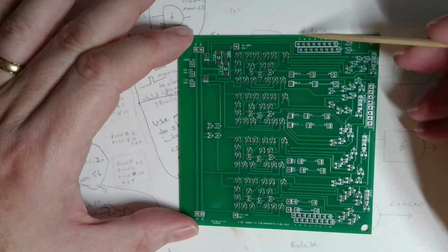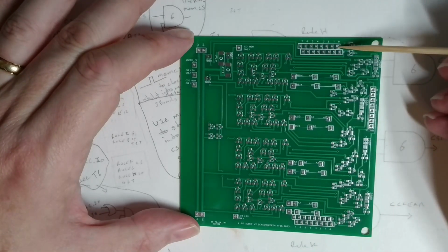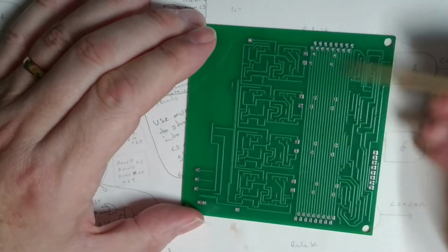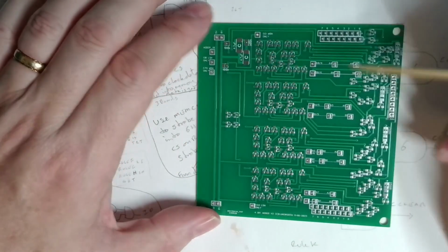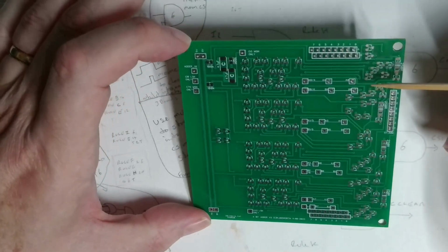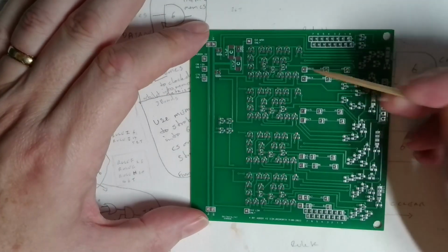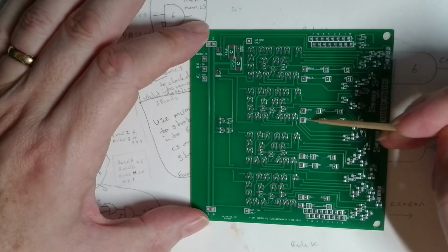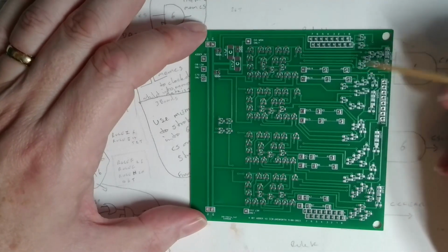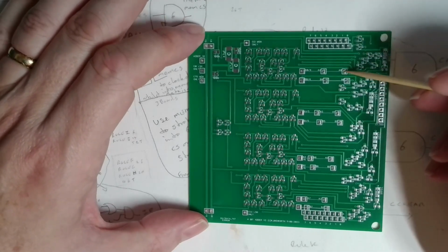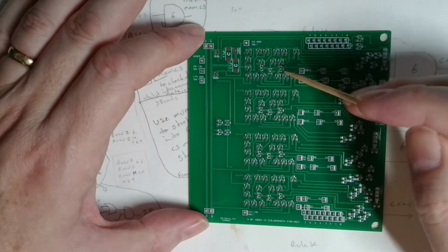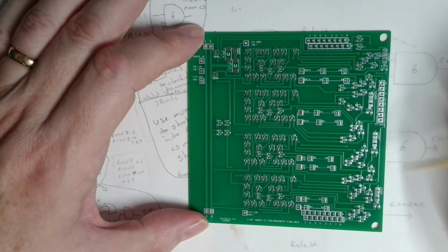So at the top here we'll have the A register coming in through these 8 bits. You run down through here, on the back there's a long bus that runs straight through. And so if you're doing the top nibble, we'd have links across to there, and that one, and that one, and that one, and as they get shorter. If you're doing the bottom nibble, as in D0 to D3, the link will come from there to there. So basically you just select which input you want to the 4 adder modules.